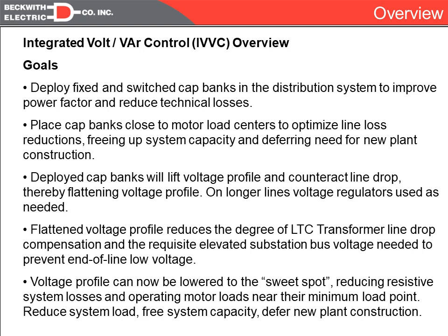First, as a recap of what we're trying to achieve overall, is an integrated volt var system in which we're going to deploy a combination of fixed and switched capacitor banks that are going to help us improve the power factor and reduce system losses. And we're also going to coordinate these as additional voltage support so that we can reduce the operations on our LTCs and our regulators, and at the same time we can flatten the voltage profile across the circuit so that we can reduce the voltage when needed and thus reduce the load. So that's the overall goal of an IVVC system.